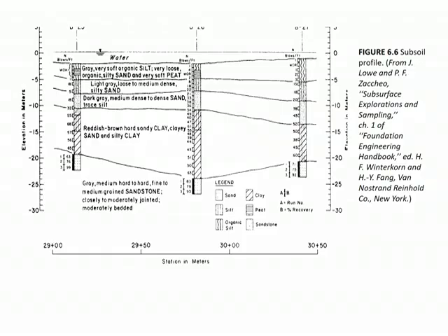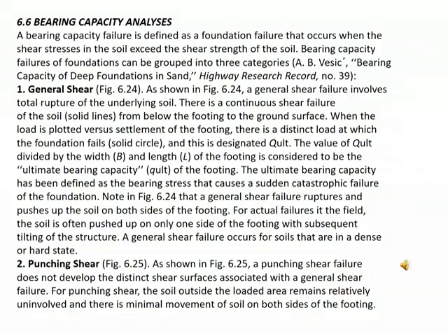The bearing capacity analysis. Bearing capacity failure is defined as the foundation failure that occurs when the shear strength of the soil is exceeded. So when bearing stress is imposed on the soil, and this load is greater than the strength of the soil, the foundation can fail. The foundation failure can happen because the soil does not have the capacity, does not have the strength